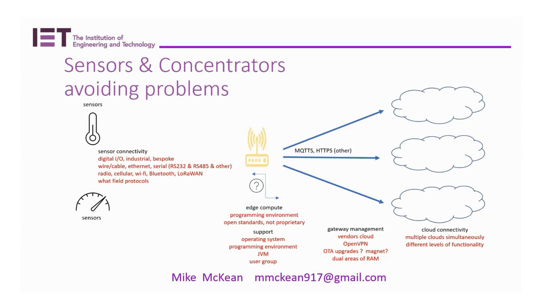Here it is. So I know I'm labouring it, probably. Oh, I'm sure I am. It's just where I see all the problems, because the people at the back end think that what they want here at the back end is an application on their phone. What they're forgetting is that this end, if you can't connect or you've got problems or you have to change things, this is where the real costs are. It's where the problems are, getting the right sensors installed. So think about your field protocols, think about your connectivity. This device is key, really is key, because it connects this end, the field end, to the back end.